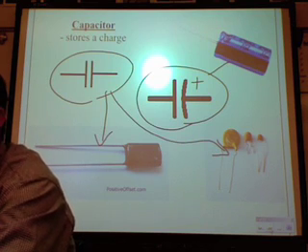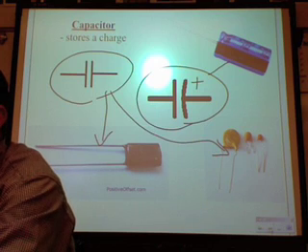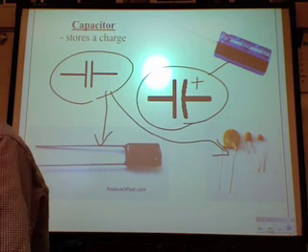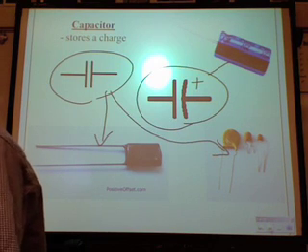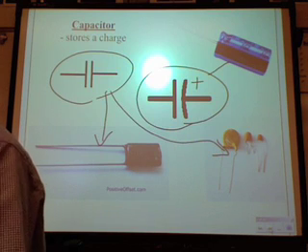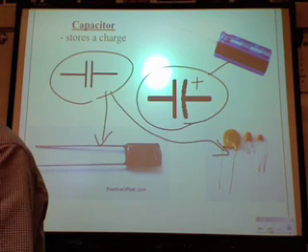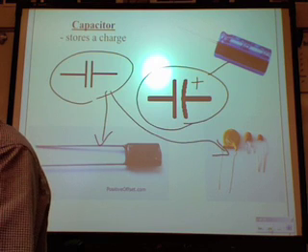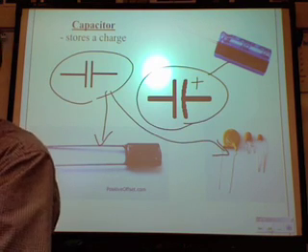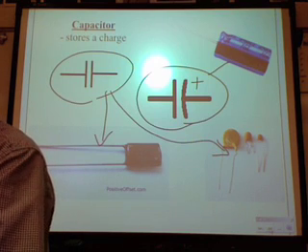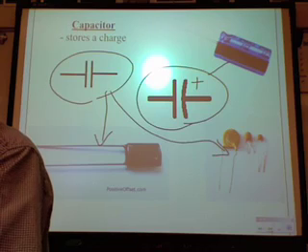So what I do then is I take that thing out of their stereo, and then I go into an electronic supply place, and I say to the guy behind the counter, oh yeah, I need a 35 volt, 1,000 microfarad capacitor. Like I know what I'm talking about. And he goes to the back and he brings one out. That'll be 35 cents. And I spring for the 35 cents. And half an hour later, I've soldered in a new one of these, and the thing works fine. Now, I don't know what I'm doing, but I can read off a label, and I can go buy something that looks just like it and works just the same.